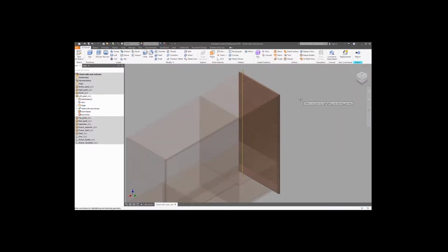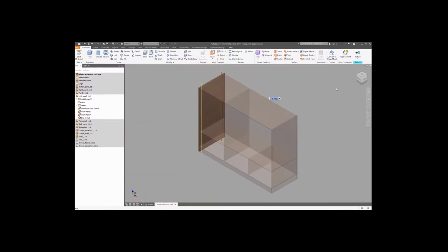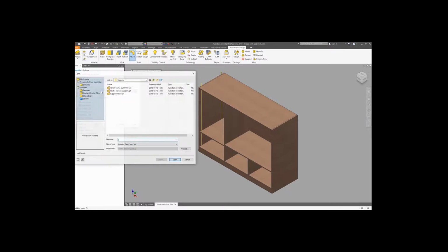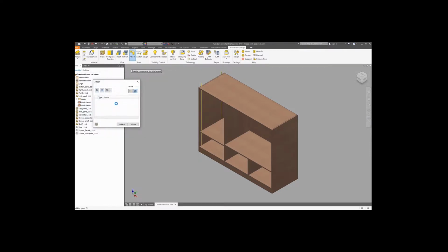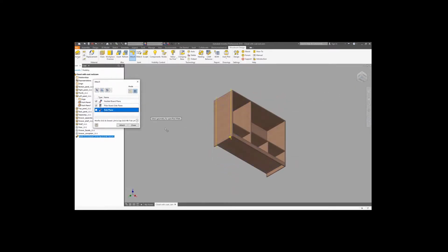The same can be done from the opposite side. Make sure that you are defining the distance, including the backplate position. Okay, so now we can use a join command to browse through the library of the components, and in between the fixed joins we will utilize the minifix. Quite a commonly used object. So here we will choose a default configuration, and then to place the component we need to define where it will be resided. Just answer the question by indicating where the appropriate components are.